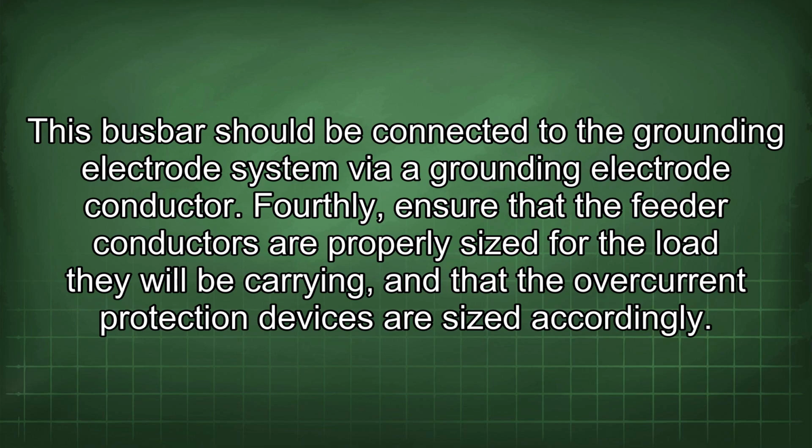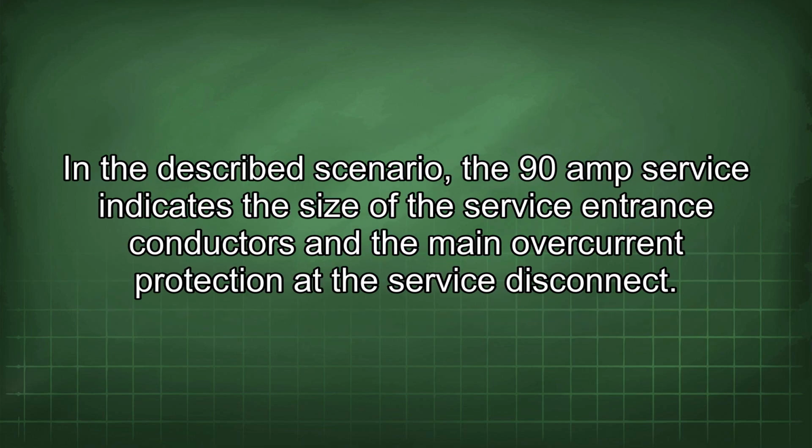Fourthly, ensure that the feeder conductors are properly sized for the load they will be carrying and that the overcurrent protection devices are sized accordingly. In the described scenario, the 90 amp service indicates the size of the service entrance conductors and the main overcurrent protection at the service disconnect.